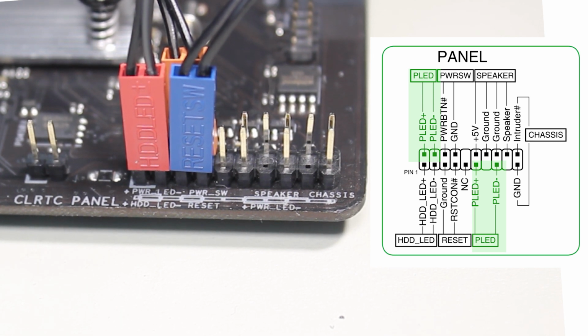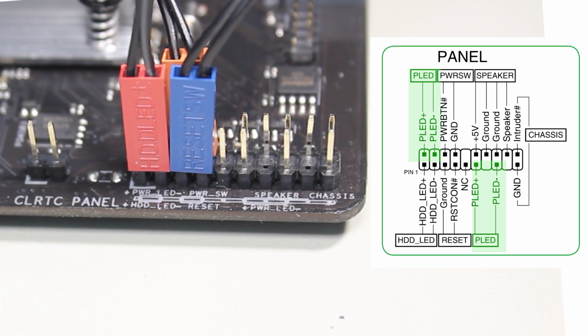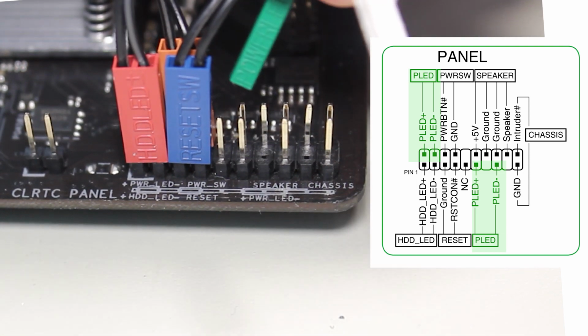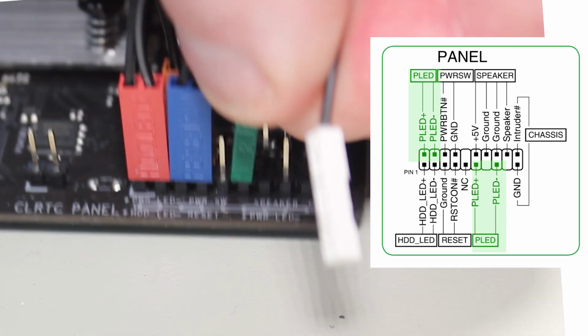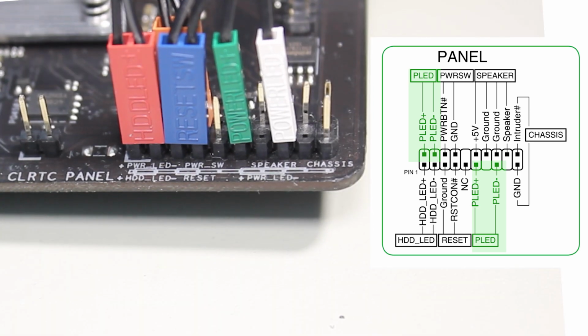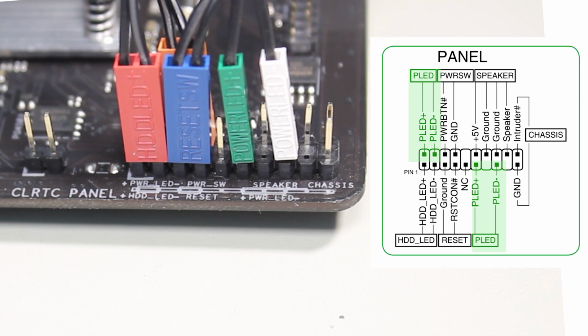Nowadays, motherboard manufacturers tend to provide the 2 and 3 pin versions in their front panel header. It does not matter which one you choose, as they will both work the same. In this case, I will use the 3 pin, making sure the positive connector is connected to the positive pin and the negative connector is connected to the negative pin.